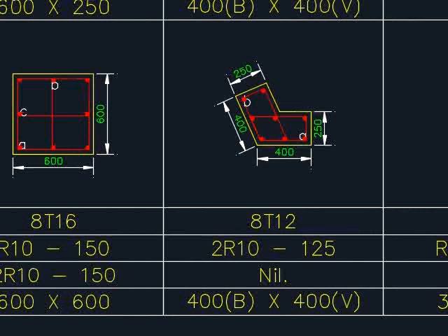In fact, you need to design for the surface cracking in accordance with the standard. But as a simple rule of thumb, you need to maintain a clear spacing of less than 300 mm between the reinforcement bars. At least from here, you will know that surface cracking is not a concern to the structure.